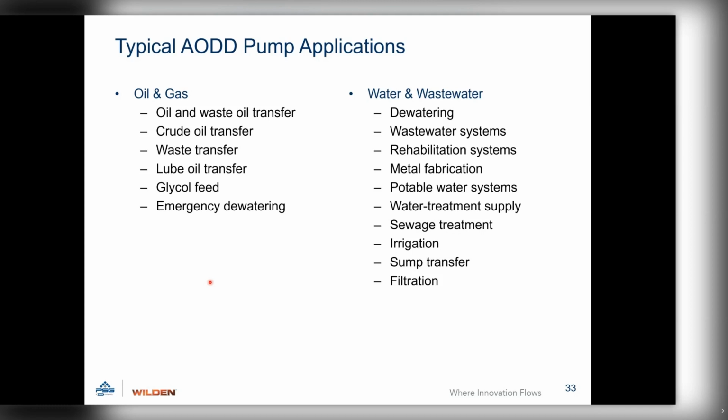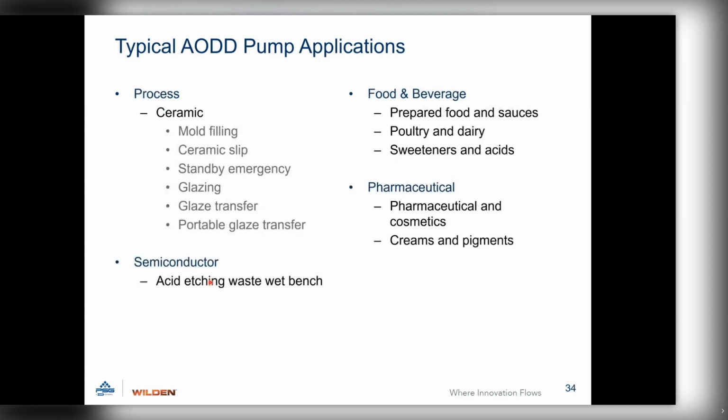And that's the gist of our diaphragm pumps, right? More and more, we're starting to see these get into the chemical process, mold filling, ceramic slip. And the diaphragm pump is good because they don't run as fast as some of the other pumps. The faster those pumps work, the faster they wear the parts out. So the diaphragm pump cycle is pretty slow, so we're able to get some really good life out of the diaphragm pumps in the ceramic industry.